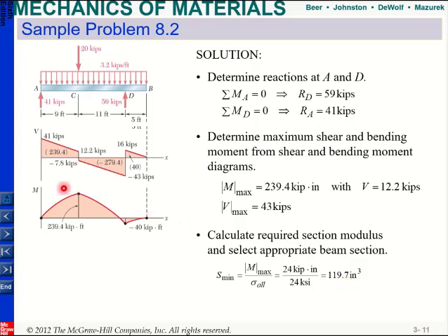Ideally, you need to look at all the points, and you can do that if you use the finite element method. But in this class we are not using it, so we need to start somewhere. What we do is design according to this point C, and then check if it works everywhere else. This is why I will start at this point, since my section modulus is not given.